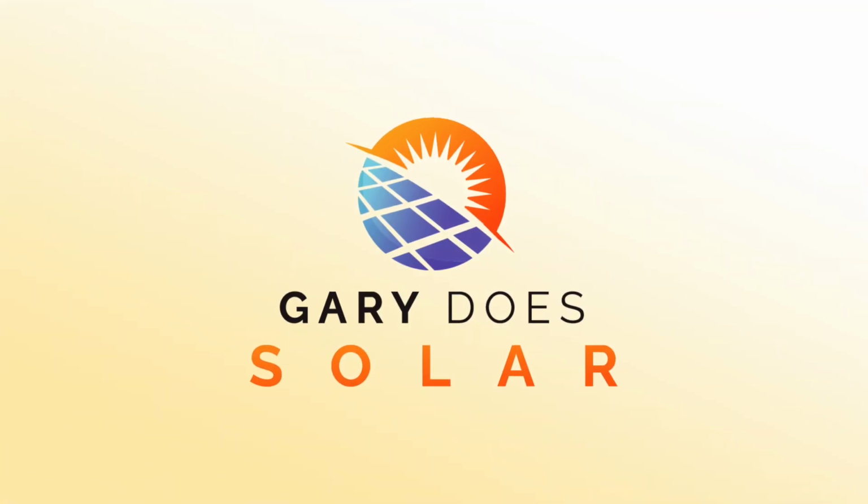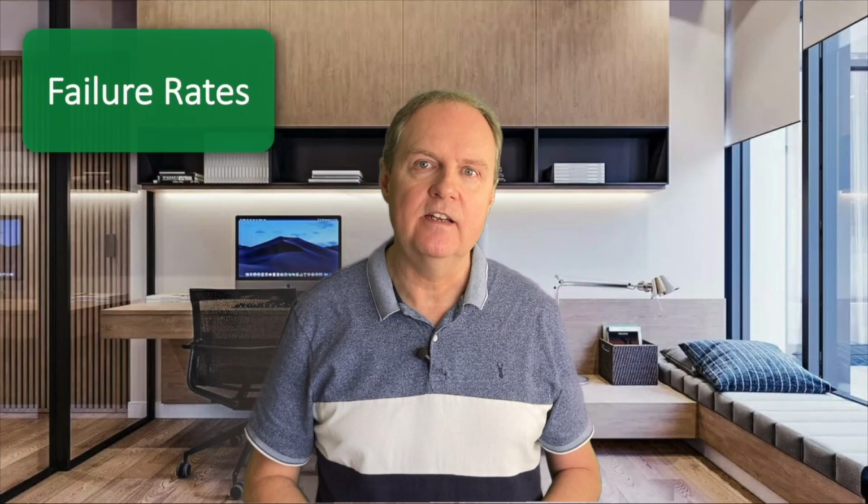For example, if you only get shading for part of the day and only on some of your panels, you might find that the gain you'll get with optimizers is only 2 or 3% anyway, remembering that your panels are already pretty good at managing shading by themselves. And we all know that the more complex something is, the more chance it will fail. So the question then becomes, will the extra few percentage points of generation offset the costs and the hassle of optimizer failures? Let's talk about failure rates then.